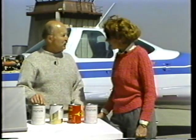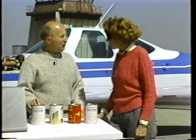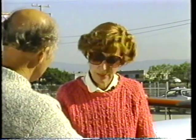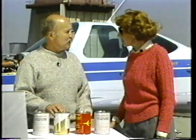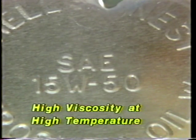The viscosity is a measure of the oil's resistance to flow. The higher the viscosity number, the more resistance it has to flow. Some of the manufacturers are now coming out with multi-grade oils, and this type of oil acts as a low viscosity oil at a low temperature and as a high viscosity oil at a high temperature.